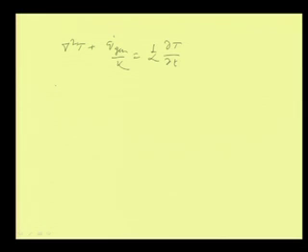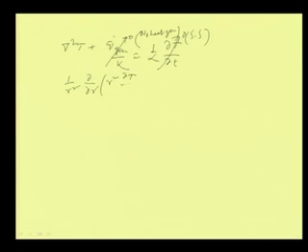What I will do here, I will straightaway write the one dimensional form, only the radial directional form of the Laplacian term. I will write, and under steady state there is no heat generation, so Q dot equal to 0. I will write only this radial directional part, because the heat conduction is taking place only along the radial direction. Then what we write is 1 by r square del by del r of r square del T by del r, and that is equal to 0.